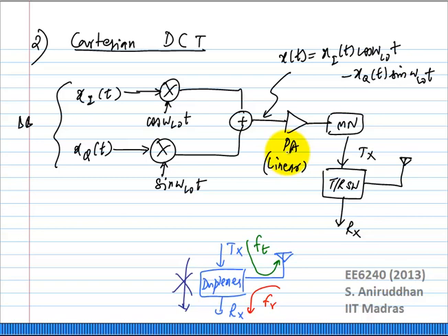Actually, it really depends on the exact system you're talking about. Because if you try to realize the switch on chip, it will naturally have a lot of loss, because the loss versus isolation trade-off in a MOSFET switch is not very good. Earlier, when we were talking about 15 years ago, the MOSFETs were much slower. So, to actually realize a low loss, you had to have a very, very large MOSFET. So, the isolation would necessarily be bad.